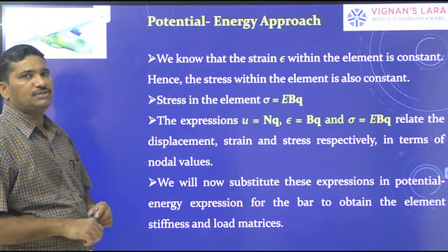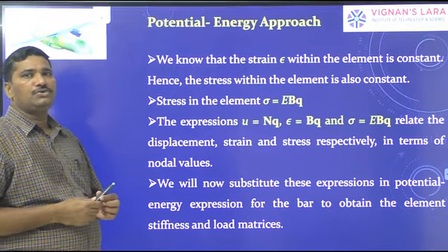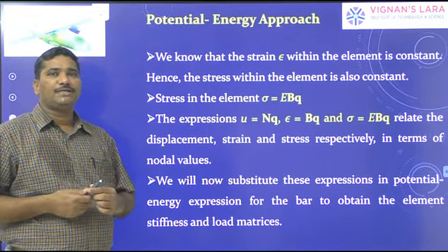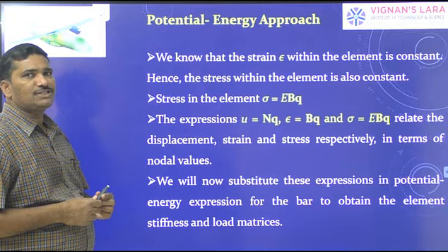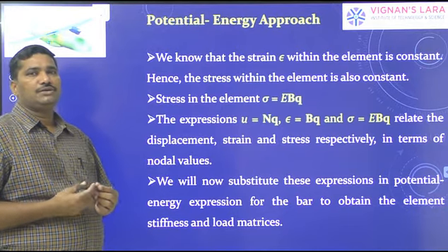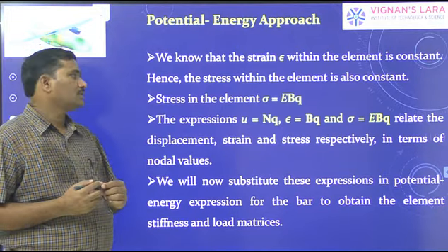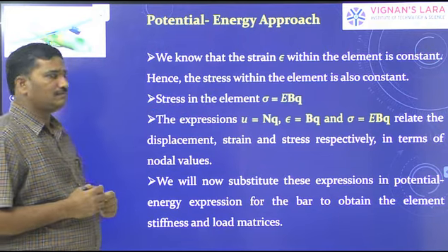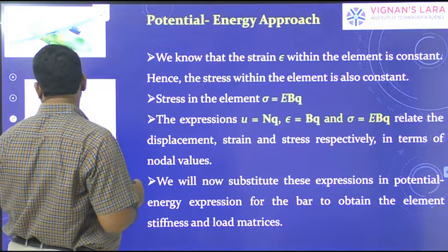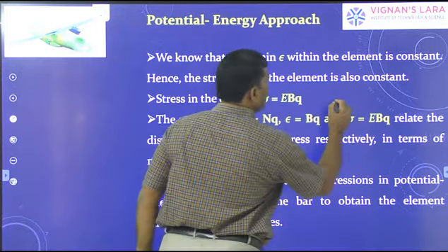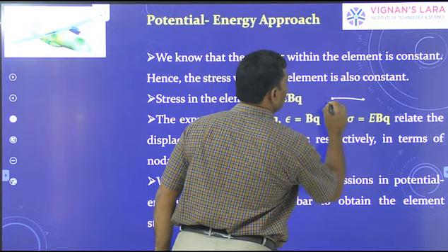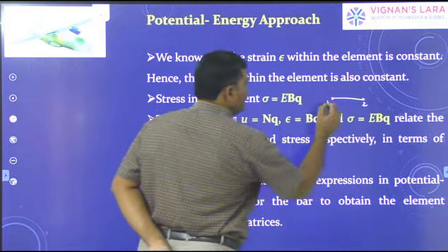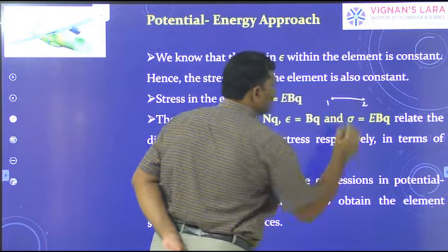Good morning, dear students. Now we shall see how the potential energy approach is useful to determine the element stiffness matrix and load vectors. We know that the strain within the element is constant. When you take a one-dimensional element connecting two nodes, the strain within this one-dimensional element is constant.